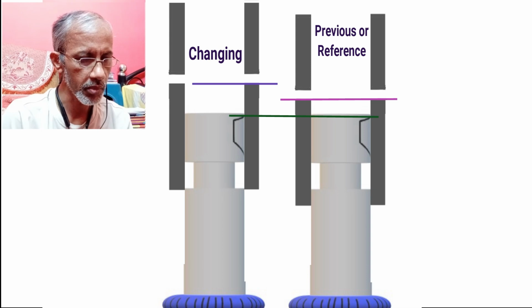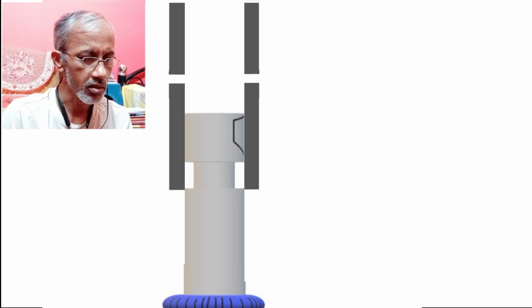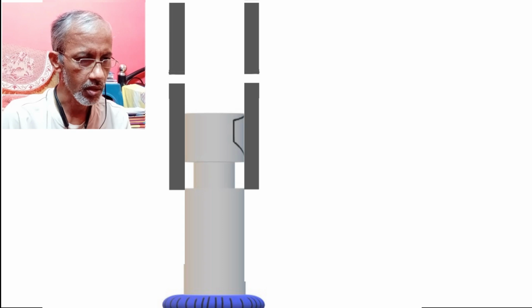So the delivery timing will be greater than that for the barrel at the reference point. So it is clear that the higher the position of the ports or the barrel, the more time is taken to start delivering, or in other words, the fuel delivery has been retarded.